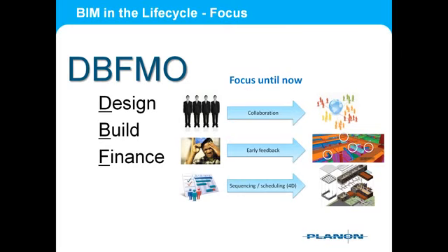Using BIM in this phase also enables early feedback on clashes that arise between construction, mechanical installation, electrotechnical installation, etc. The earlier these clashes can be detected, often the cheaper the solution will be, rather than facing these problems on the building site, which is inevitably more expensive. In this respect, a BIM pays for itself several times over.